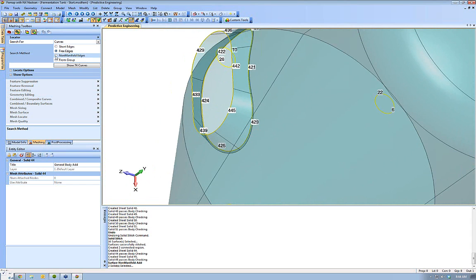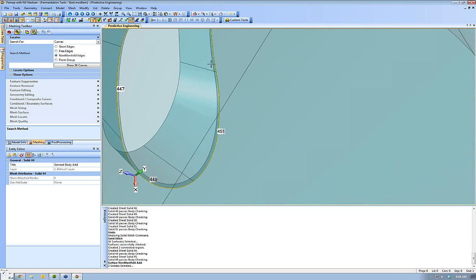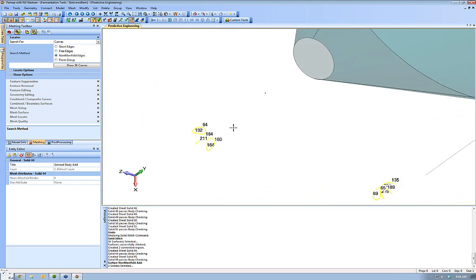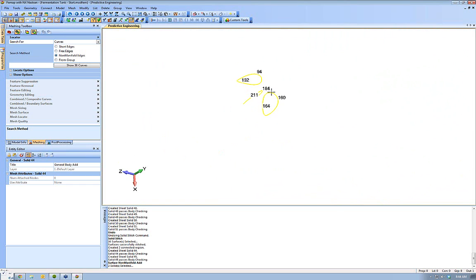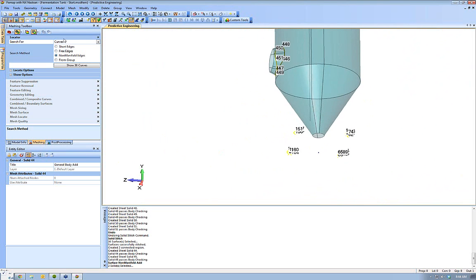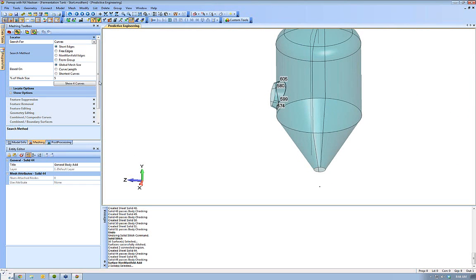Let's look at non-manifold edges. And there we go. That junction between these two pieces that required non-manifold add, that's highlighted. And then our junctions, this is a little hard to see, yellow on white, but these are the junctions of the lower structure that required non-manifold add. Another good one to check is short edges. And right now, if we go to curve length, you could choose a specific length and say anything under this size, which is 0.28 inches, highlight curves shorter than 0.28.